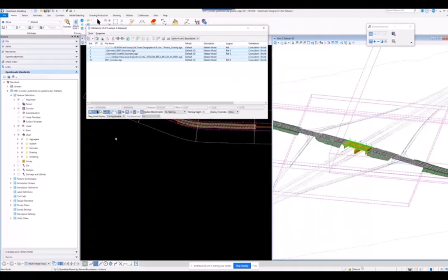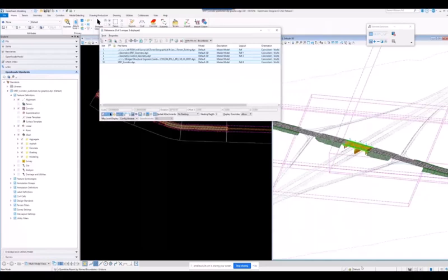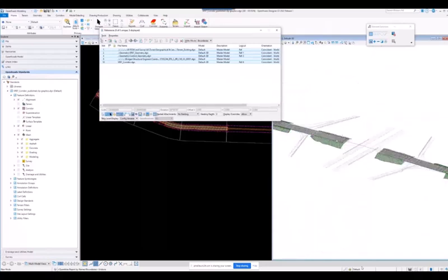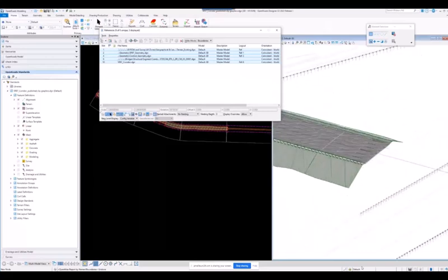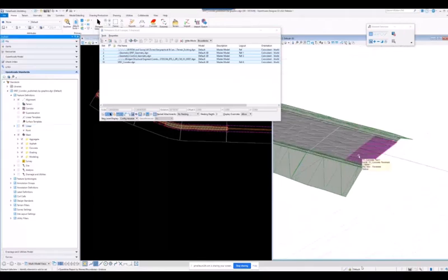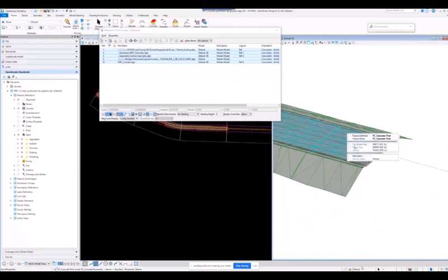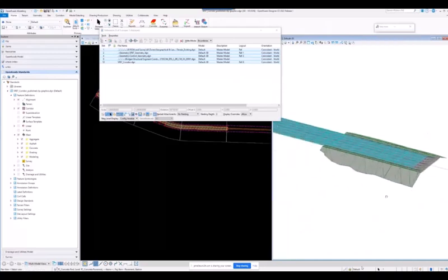So we're going to go in here in our 3D space, and we're going to just simply shut things down. I'm going to shut off the original reference files and look in here, and you can see that once I hover over these items, shut the linears off first, make it a little easier to grab. You can see that the pavement is broken right where that name boundary is. The beauty of it is when it clips it, it reevaluates the slope area, planar area, and volume, because if you're going to send it like the IFC, you're going to have the correct properties being sent across.